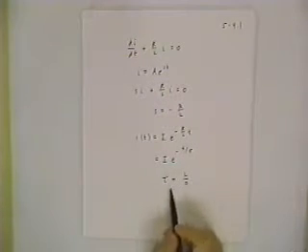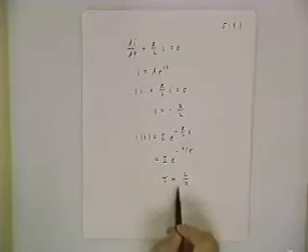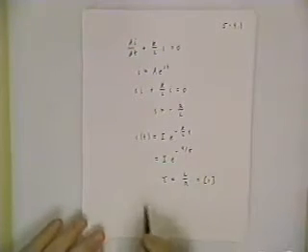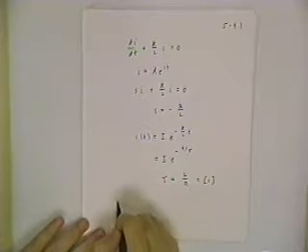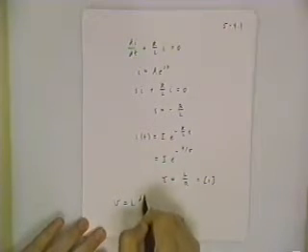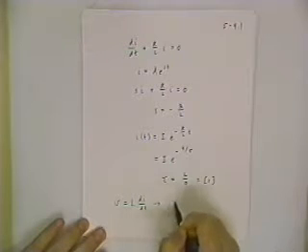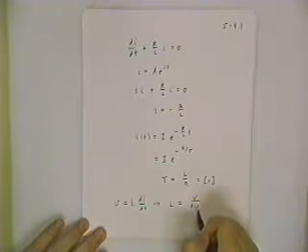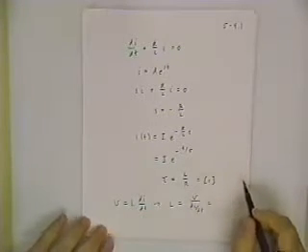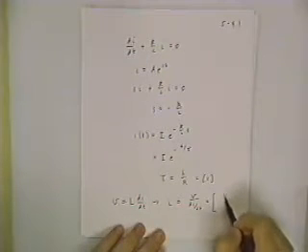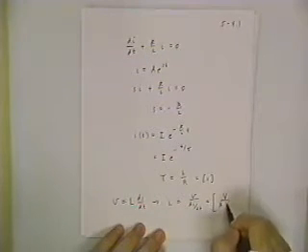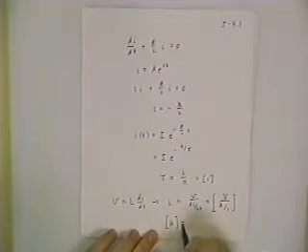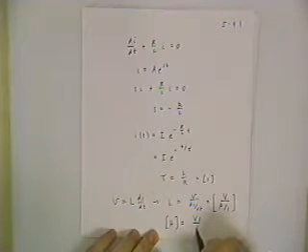Now this gives me an opportunity to talk to you about the units of inductance and resistance and where this comes out to be units of seconds. It's a handy trick from the linear model. If you remember, V is L di/dt. Then you think of that as inductance is a ratio of voltage to rate of change of current. So a unit of inductance would be units of volts divided by amps per second. Or if you like, a unit of Henry is a volt second per amp.